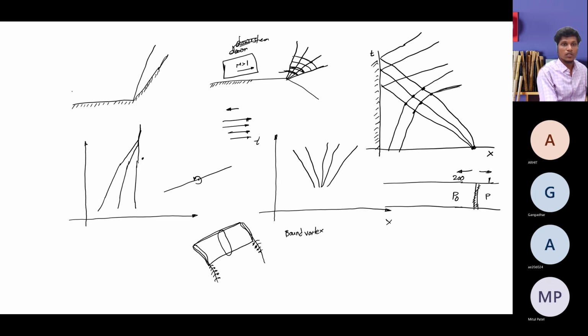Like in physics, if you have a domain and there is a presence of a vortex here, its strength exists everywhere in the flow field. You cannot say its strength does not exist somewhere in the flow field. That means it cannot end anywhere in the flow field. In the same way, a vortex filament cannot end in the free stream, and these are all combinations of vortices placed along the filament. So it cannot end in the free stream. So we model that by making it trailing vortices in the form of a horseshoe vortex.